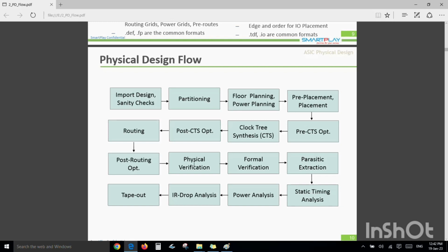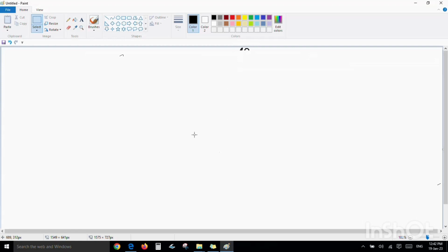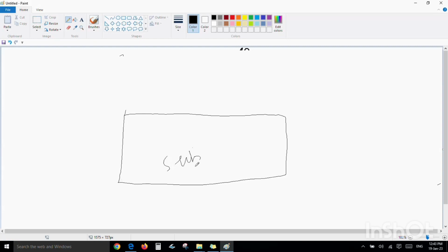We also check the width of the via, and the n diffusion, n substrate to n well distances. Let me show you the substrate. If you take it, this is going to be my substrate. This is going to be my n-well. Here I am going to place the source, and here the other n-well will be there. So well to well distance, well to substrate distance,